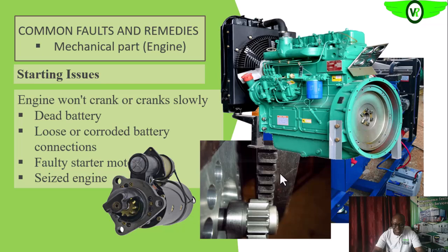So the remedies to this kind of situation are very simple. Once you notice that this one is dead, you replace. Then if the connections are loose at the battery end or at whatever end, as you are cranking, as you are putting on the ignition, you hear sparks at the battery terminal.